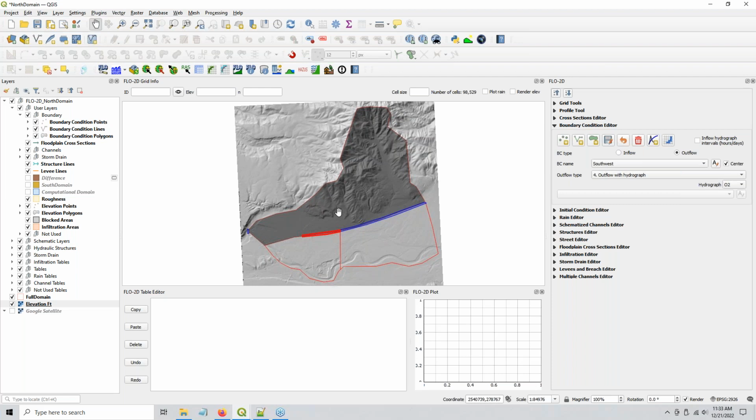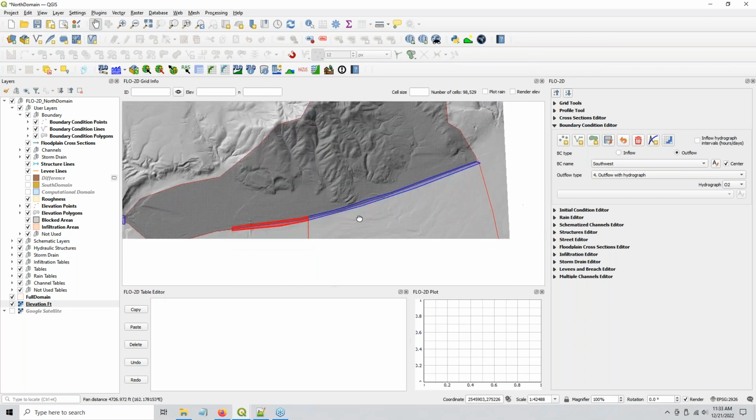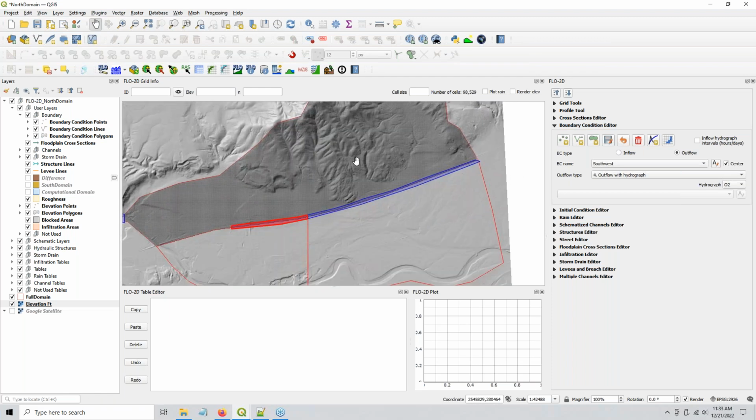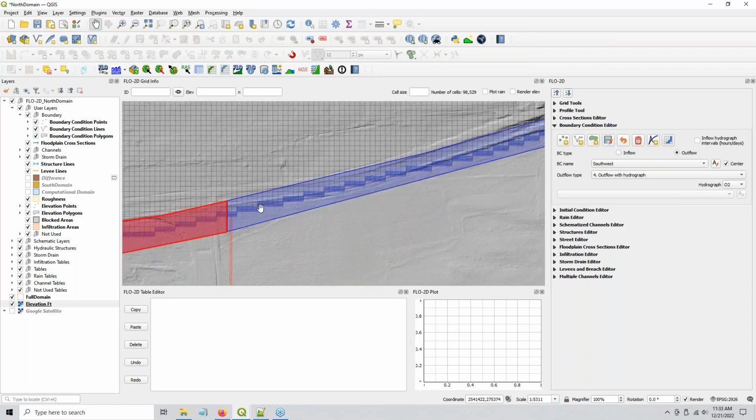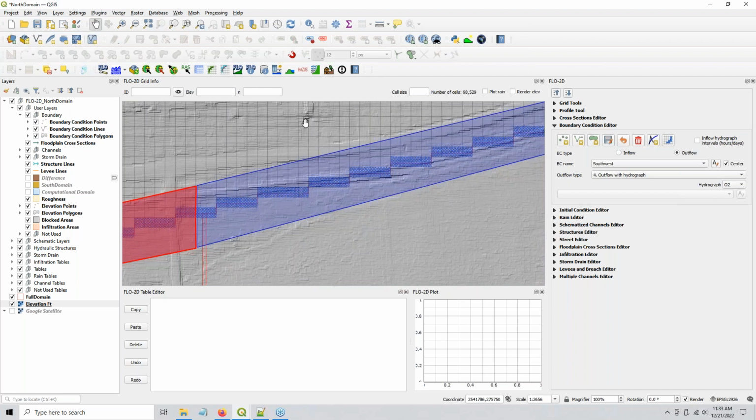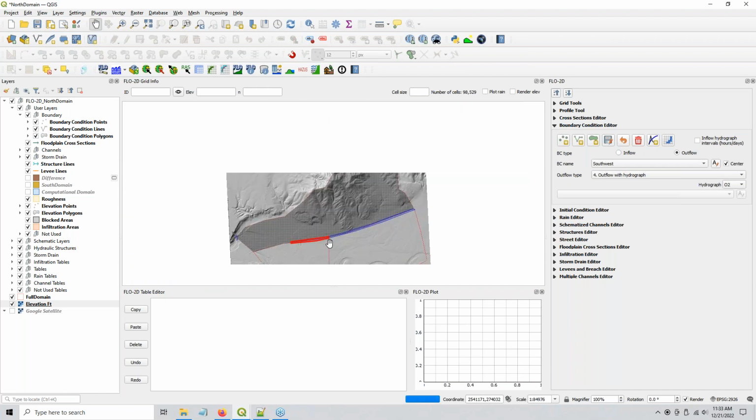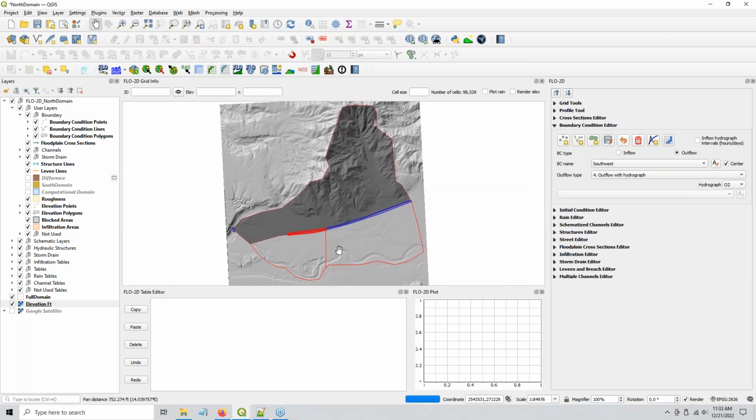This originally was like 50 up here, and then I realized when I went to overlap them that they didn't align very well. So I went ahead and modified this top one to 60 so that the downstream grid would fit into the upstream grid. It would align perfectly, and you can see that in the first video. So these are just a couple of things to help you recap. This could be all 20 as well if you wanted to do it that way, but I do try to make them align correctly so that the smaller cell size would fit perfectly inside the larger cell size.